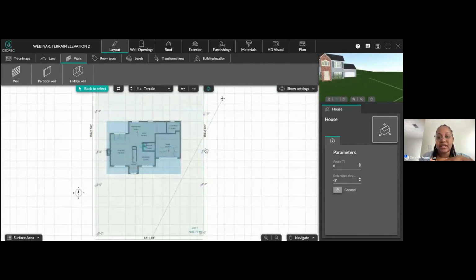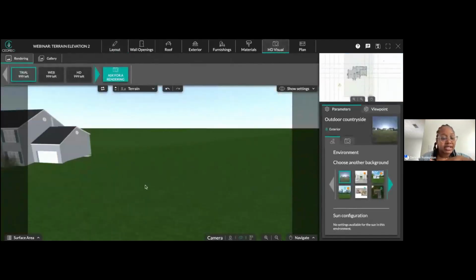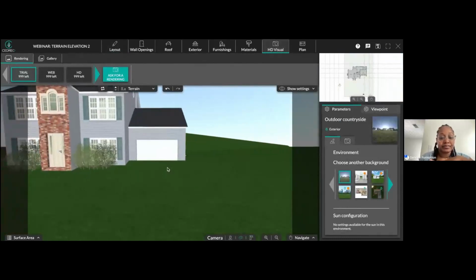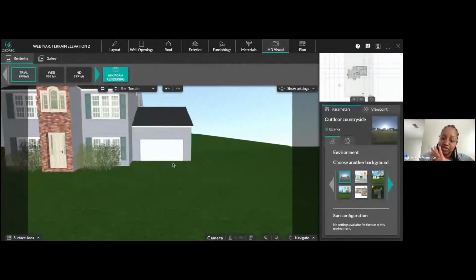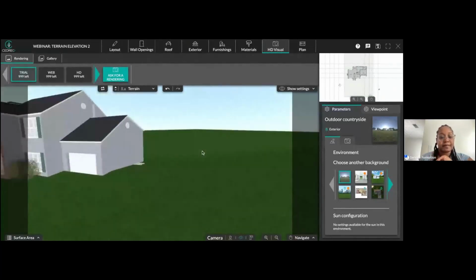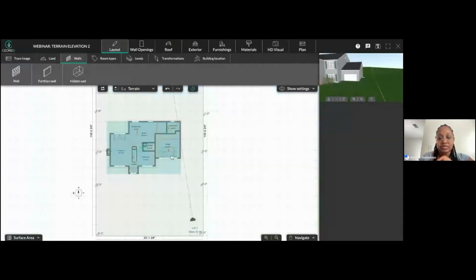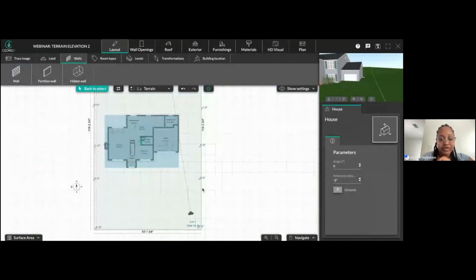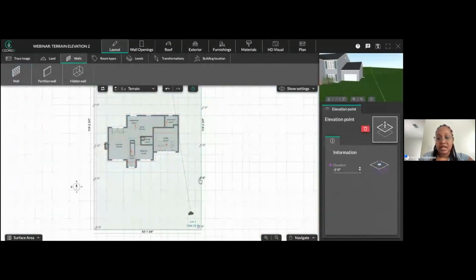And then as you can see here, my garage is kind of still further up. But we're going to fix that. Don't worry about that. We can also, over here, I'll say, okay, maybe I want to bring these points. So you can click on the points, but I want to change this elevation. And maybe I'm going to make this elevation a 0. I can click on it in the right panel. I can click on each elevation and I can reduce it down to 0.